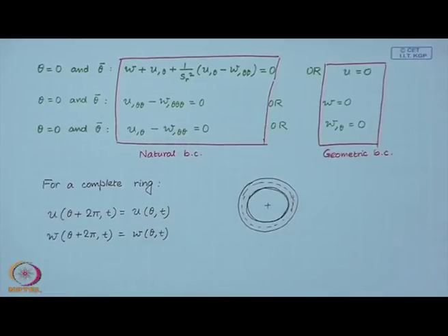So, everything is going to be periodic. So, displacement, slope, bending moment, shear force, etc. are going to satisfy the periodicity conditions. So, for a complete ring we have these two conditions.